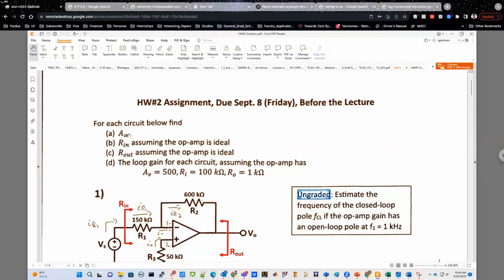Okay. So what is happening to the open loop gain of the op amp? It's getting divided by almost T0 times, assuming that T0 is very high. Now you had a question yesterday: what if T0 is equal to 1? Right? That your beta is equal to 1 upon A. Right? That's the question you had.